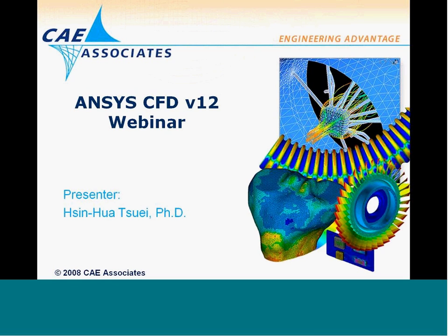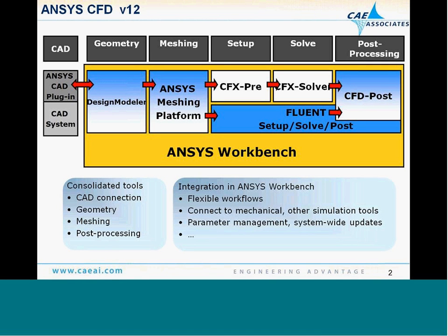First of all, I have a couple of slides to show the ANSYS Workbench environment and all the pieces integrating into the Workbench environment for a CFD analysis. In this diagram, with any CFD analysis, we need to have a geometry. And in ANSYS, we use Design Modeler to handle the geometry. Either we import a geometry from a CAD system, or you can generate your geometry in Design Modeler.